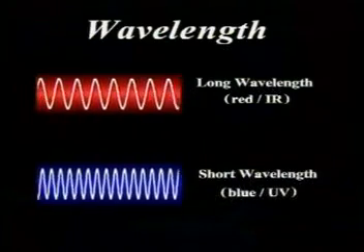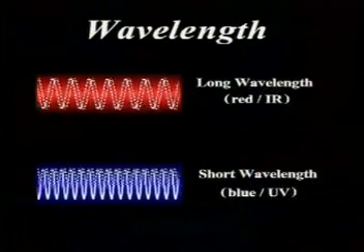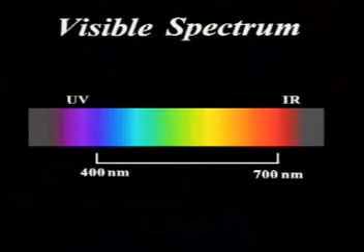Part of the spectrum, the wavelength of light determines its color. Optical wavelengths are measured in nanometers, or billionths of a meter. Blue light has wavelengths of around 400 nanometers, while red light is approximately 700 nanometers. The infrared area starts around 800 and increases to about 100,000 nanometers as it approaches the microwave region. It is the infrared area we are interested in for most fiber optic applications.